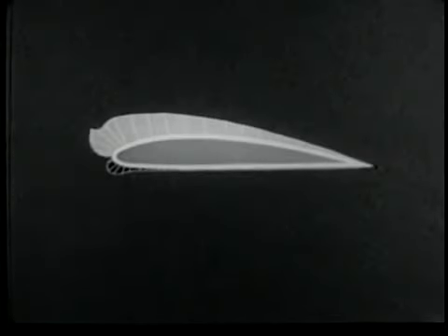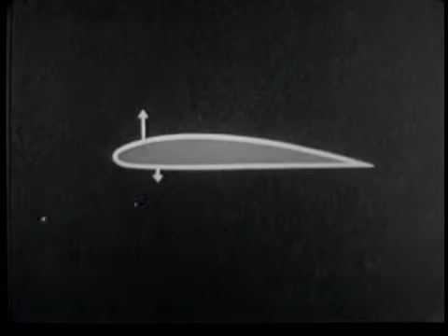An airfoil at rest in still air is at atmospheric pressure over its entire surface. It has been shown that airfoils derive their lift from the pressure differences acting upon their surfaces, the negative pressure difference upon the upper surface at normal angles of attack being the major component of the lift force.